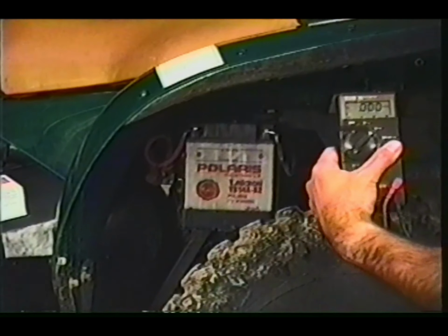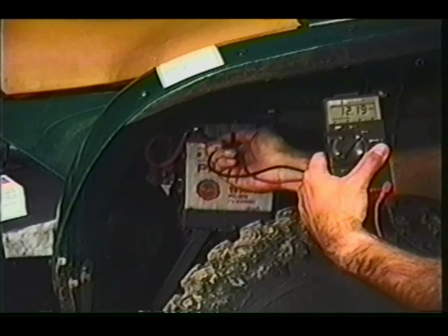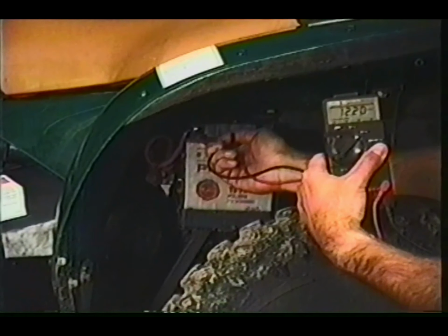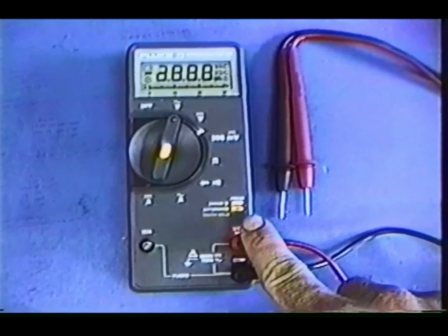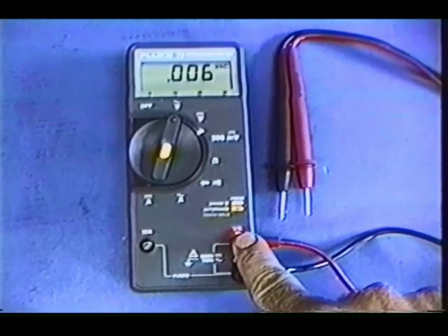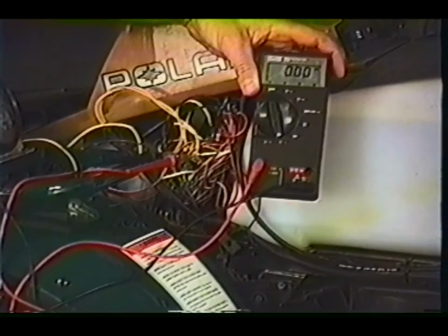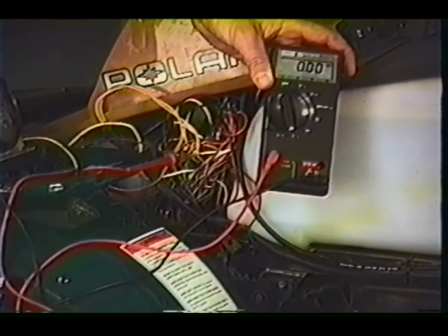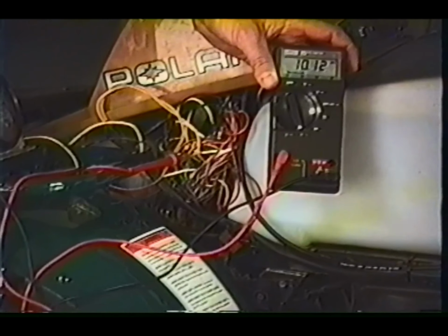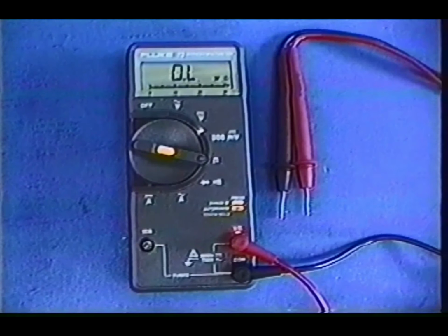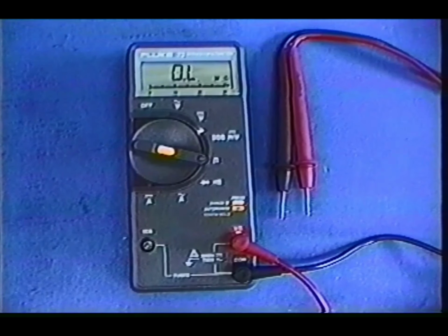The tests we've discussed up to this point will identify problems with the battery and system loads. The following three tests can be used to verify proper output of the alternator. First, the AC open circuit voltage test will indicate the voltage pressure available to the rest of the system. Next, the AC amperage test will simulate full alternator load. The reading observed should be close to the maximum current the alternator can supply. And finally, a resistance check that will test for a short or open circuit in the stator coils and the wires leading to the coils.